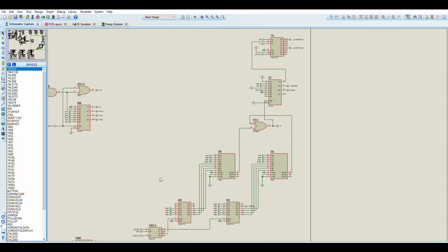And what it means is that when you start rendering a 32 by 32 pixel sprite from that particular index, it would basically internally skip over the sprite definition and the palette and the X and the Y position. It wouldn't read those, it would just reuse what had been read from the previous one, but it would continue on with the horizontal position or the vertical position. And what that meant is that the hardware very cheaply and simply could start rendering double size or quadruple size sprites with very little extra logic. This is what this does.